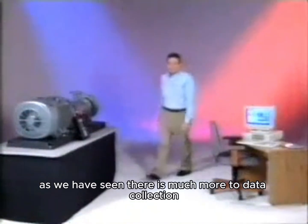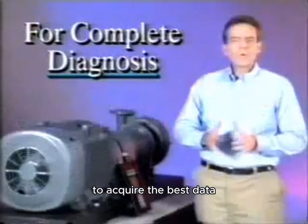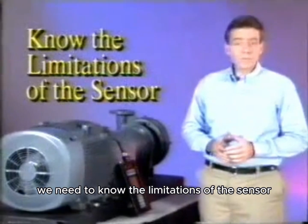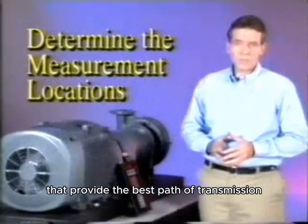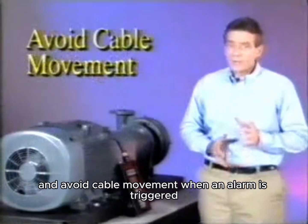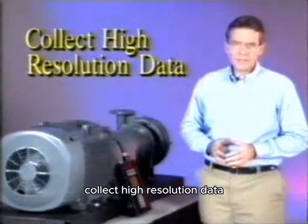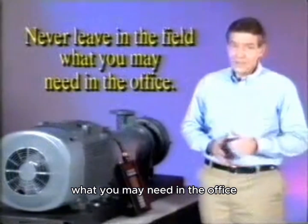As we have seen, there is much more to data collection than just placing a sensor on a machine and expecting a complete and comprehensive diagnosis. To acquire the best data for the most complete diagnosis, we need to know the limitations of the sensor, determine the measurement locations that provide the best path of transmission, and mark the machinery to ensure repeatability. During data collection, allow for settling time and avoid cable movement. When an alarm is triggered, collect high-resolution data and take notes of any observances. Never leave in the field what you may need in the office.